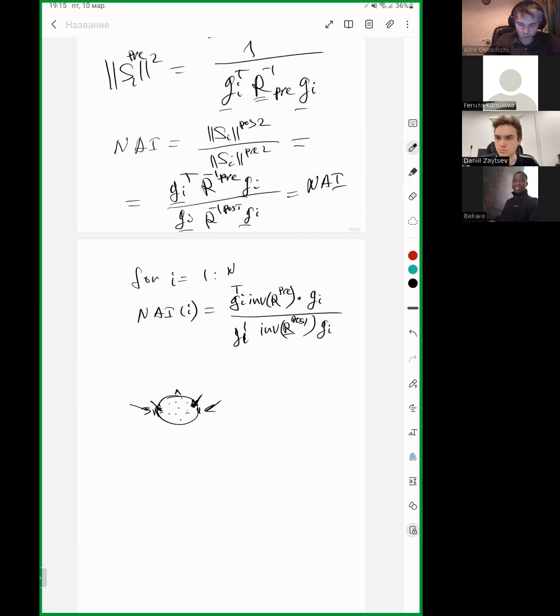Because of the synchrony, when you are beamforming for a location in this one, the beamformer will use synchronous power of sources in this other location to cancel, to minimize the output, and therefore will screw up the entire distribution. This is actually very similar to how the jammer works.